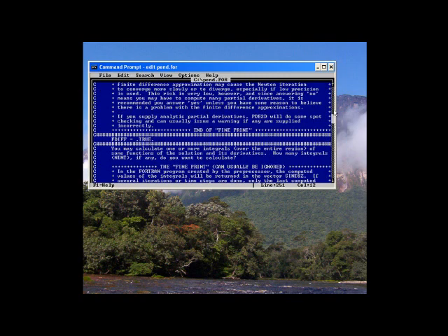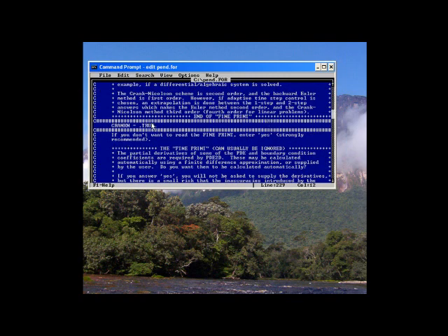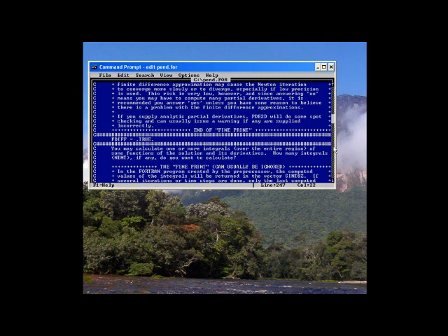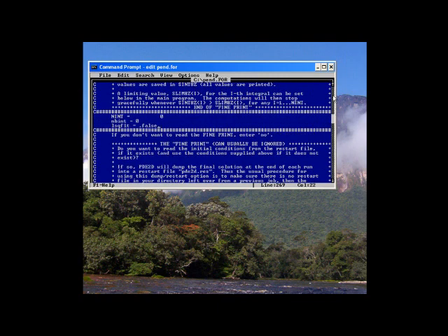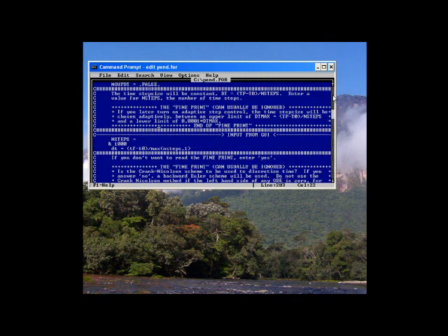And there we go, Crank-Nicholson equals true. That's the default, but for this problem, it's just not a good idea, and you would have no way of knowing that except the book tells you. And I believe that's it because adapt is already set to false. Yeah, we already checked that.